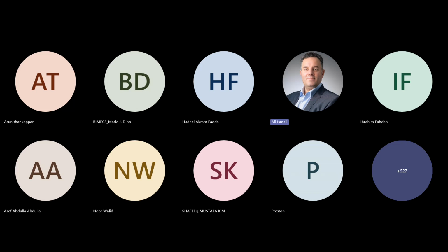Question related to whether stairs and ramps should be part of the architectural discipline or structural discipline. Yes, you have a right. Maybe we started at the beginning by adding them to the architectural model, but in practice they are better added to the structural model. If you are submitting a BIM model only for architecture and you are not mandated to submit a structural model, please add the stairs and ramps to the architectural model.